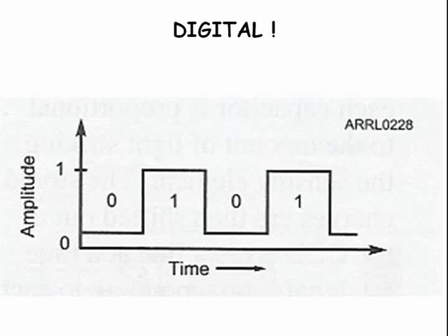Our next subject is digital electronics. In binary digital systems, you may have only two states, 0 or 1, an off or an on, or a mark or a space in communication systems. Digital systems are created using digital integrated circuits. In binary digital logic circuits, each combination of inputs results in a specific output or combination of outputs.